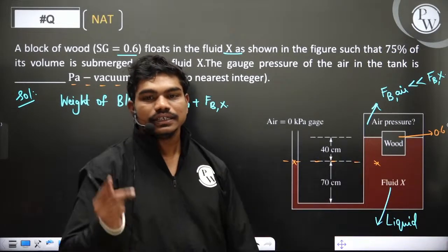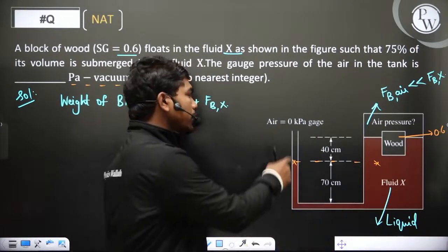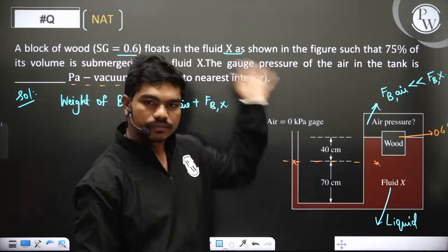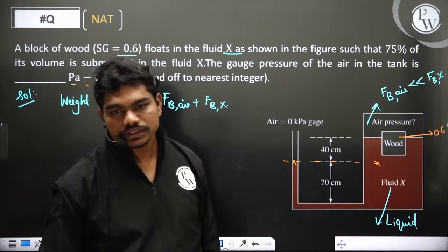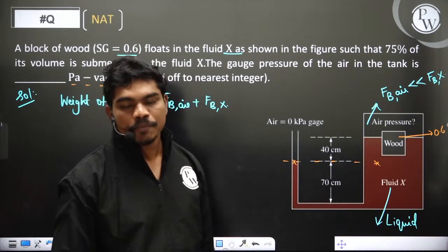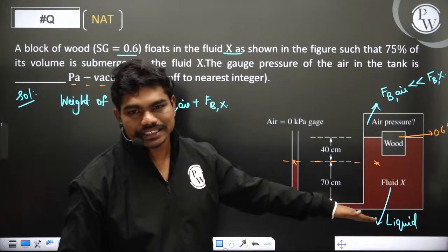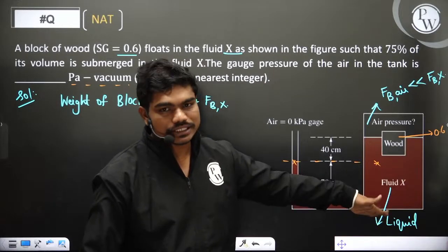Obviously it's yes. Second, I can confirm it's still liquid, because if this is gas, you cannot use an open tube. Yes or no? If it is gas, this open tube will bypass the gas, okay? Because of these logics, we can say this is definitely liquid, with a density of at least more than 600. We don't know the density right now, but we know it has density more than 600, okay?